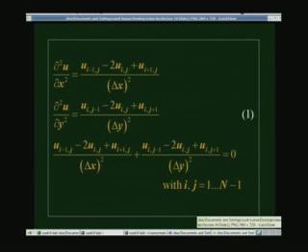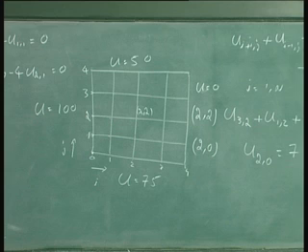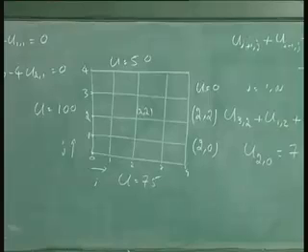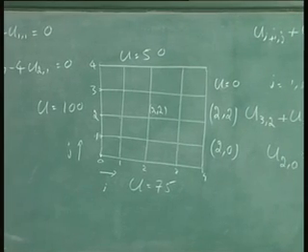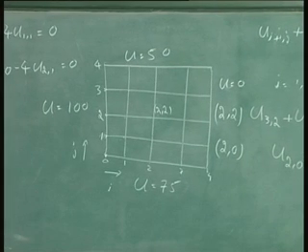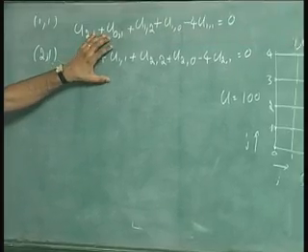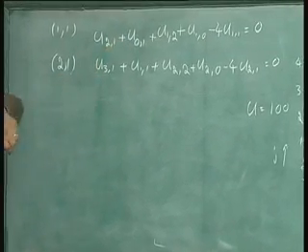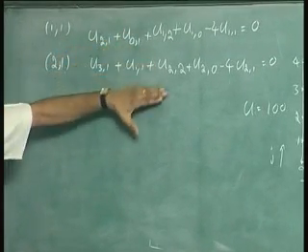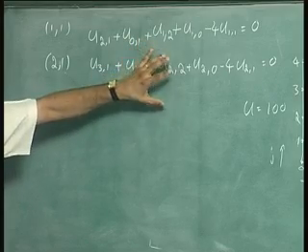Now let's look at a specific example where we implement this simple boundary condition, that is, fixed temperature at the boundaries. And then we solve 9 such equations linearly. It's obvious that we can solve these equations by the matrix methods we know. We have these 9 equations, and we can just invert this matrix using matrix methods.